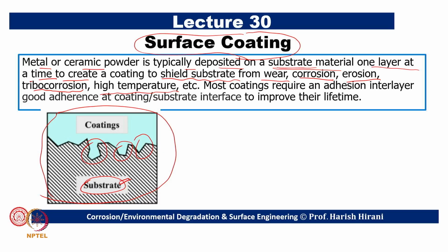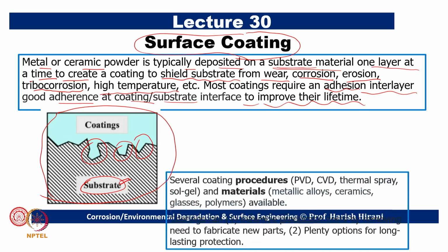As I mentioned, either we go ahead with a good surface preparation and there is a mechanical attachment between coating and substrate, or otherwise we may go ahead with some sort of interlayer, an additional interlayer, for good adherence at the coating and substrate interface. The reason is to improve the lifetime of the coating. So, these are the important aspects.